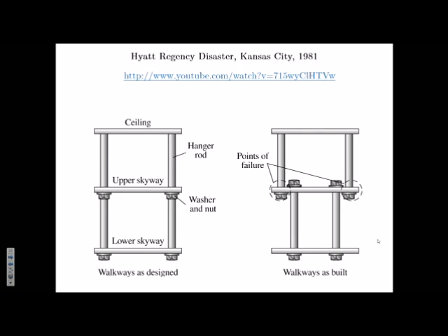Another reason that is not mentioned in your textbook, which I know, is that if you look at this design, right, we know that wherever the nuts are, that's where the threads have to be. Okay? Now, when you cut the thread, the effective diameter where the threads are cut would be less, right? You have to pass this nut, which has to fit the thread, which means that the diameter over here of the rod would have to be smaller too.